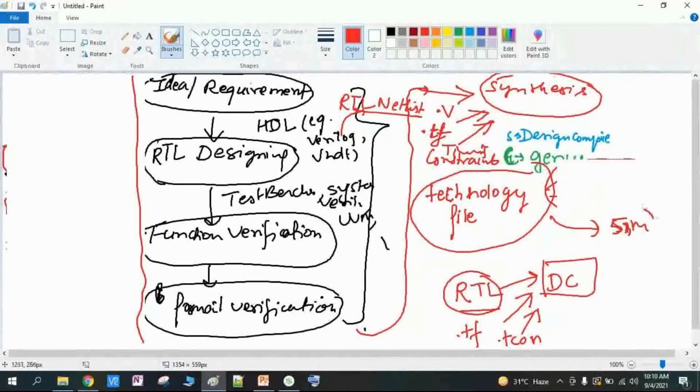So using this 5 nanometer technology, you are going to design whatever logic you have written. Now in that designing, a lot of new rules will be there, because when I'm going to place those logic in my real tool, then for example, if this is one logic, this is other logic, then spacing between those logics rules will be defined. The width of the particular object also will be defined. All those rules will be defined in the technology file, and those rules will be different from technology to technology. That will be given by the foundry.